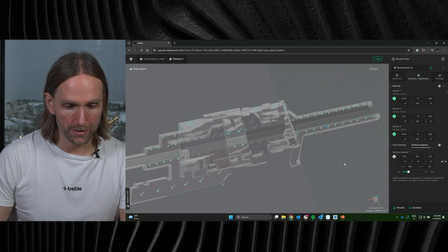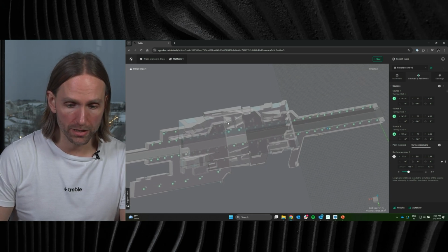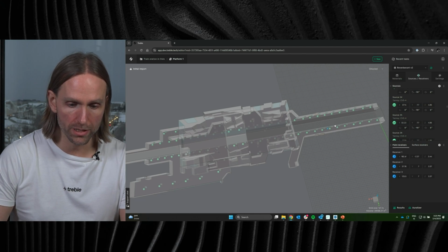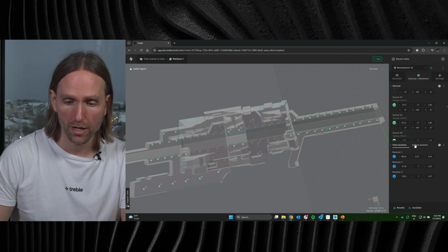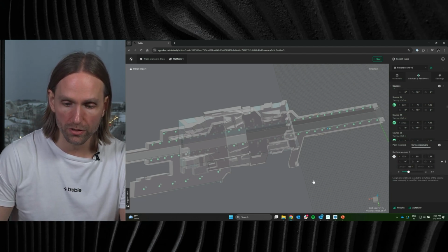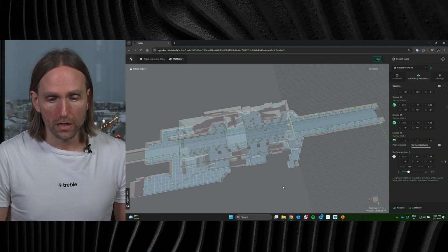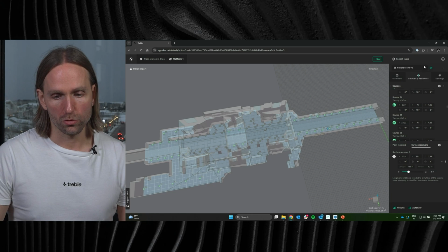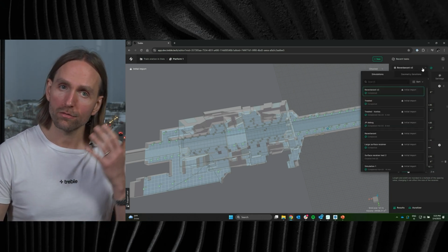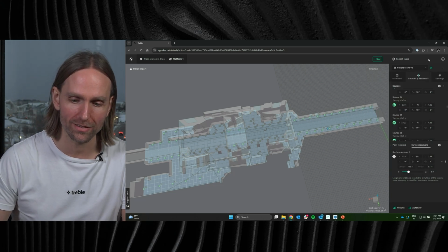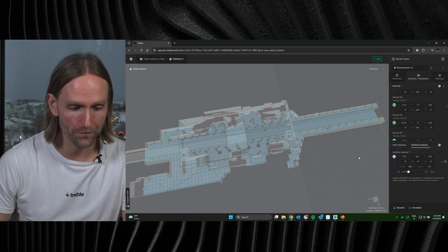As I said, I have put in 72 of these sound sources. I put in a few listening positions in case I wanted to do auralization, and then I put in this very large surface receiver as well, which has around 1,000 grid points on it. And I've simulated this for 2 acoustic conditions, just for fun, as always: more acoustic treatment, less acoustic treatment, so we can compare some results later.